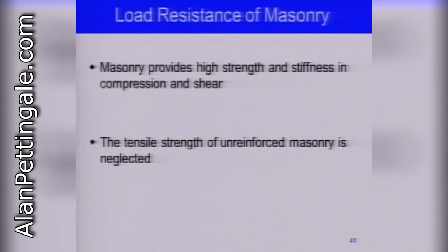Then we go to the load resistance of masonry. Masonry can provide very high strength and stiffness in compression and shear. So you can compress it as much as you want. I mean, okay, at some point it will break, but usually it breaks at way higher loads than what it is typically loaded at. Masonry structures are typically loaded at around, let's say 10, 20 would be an exaggeration, percent of their actual strength. So they have a lot of safety and a lot of capacity in terms of compression.